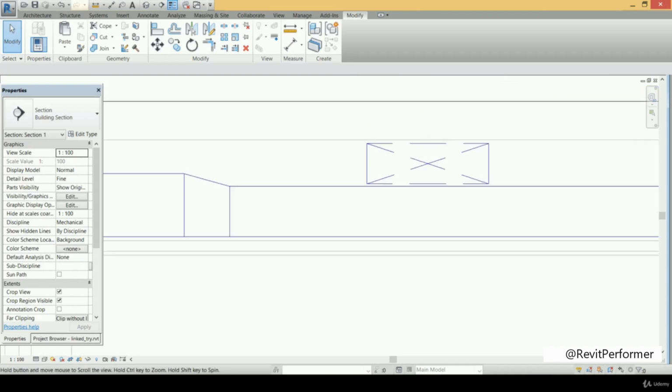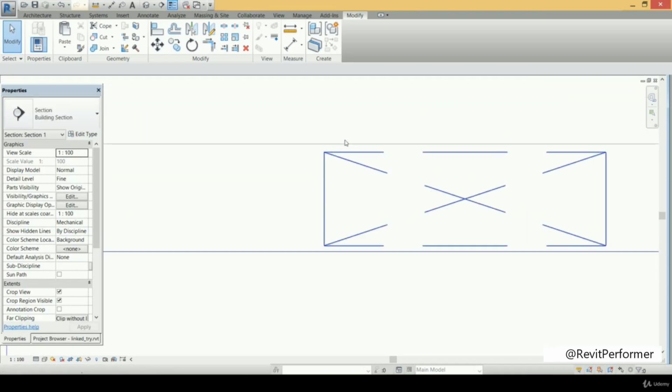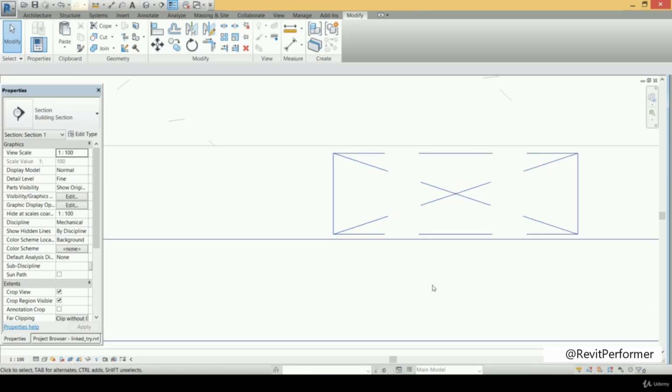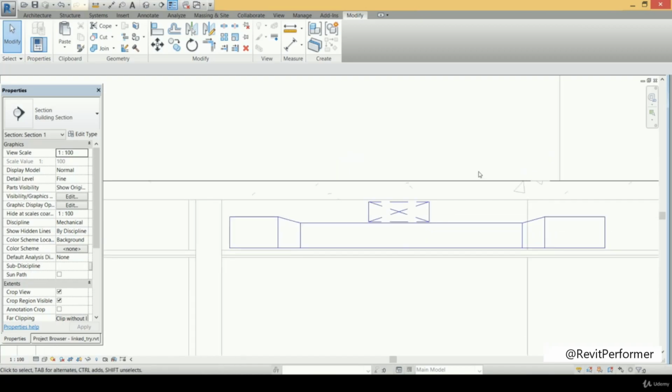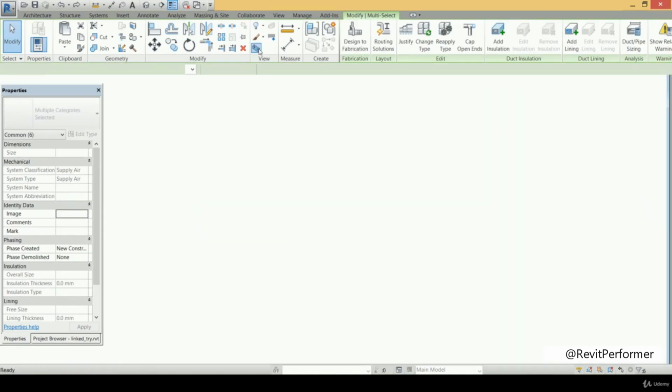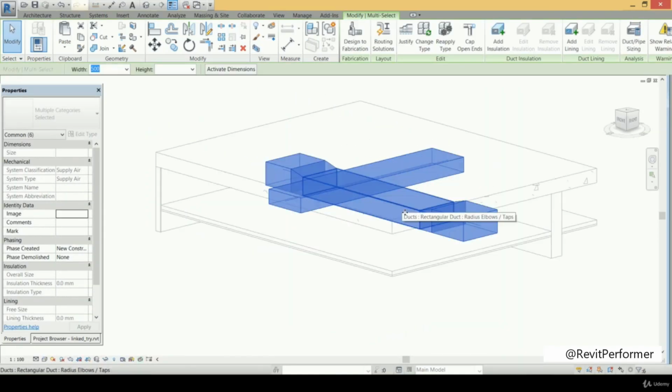And also for the upper surface, we will find that we have a distance here from the upper concrete ceiling and the upper duct. And also we have a distance between that vertical duct and that horizontal duct. Very good. Now we can see that also in the 3D model. So if I close that tab and I press on that selection box to see them in 3 dimensions, as you see, those are the two ducts that we have.